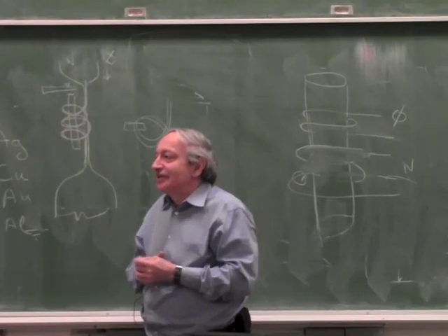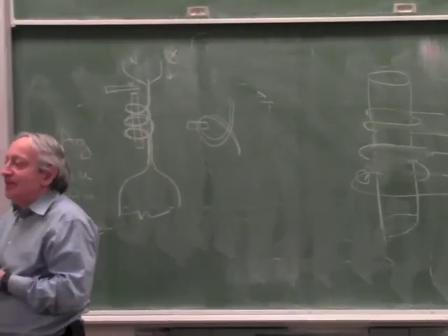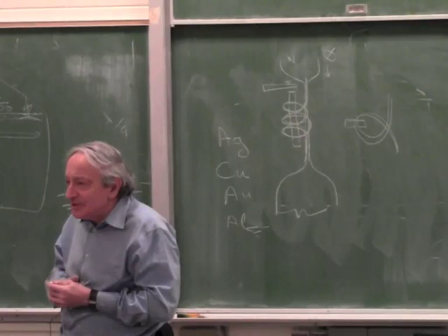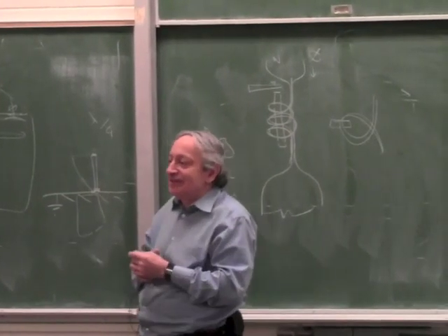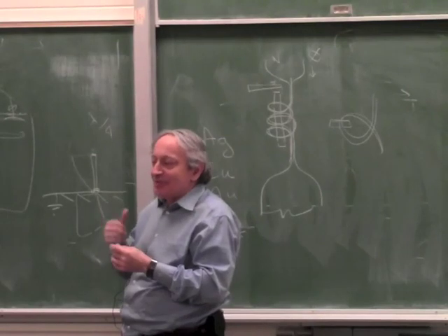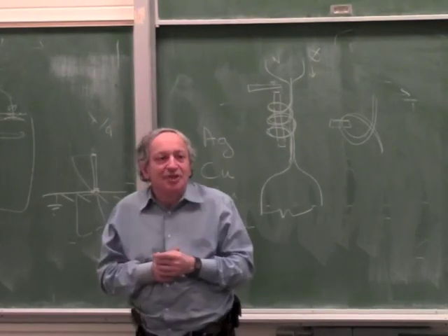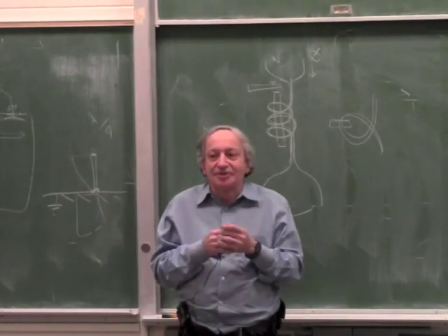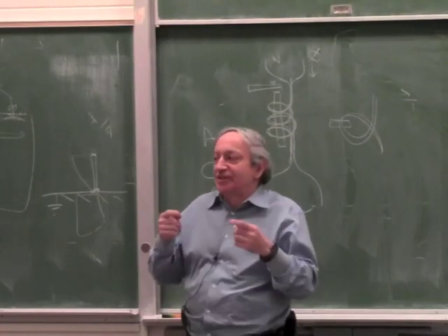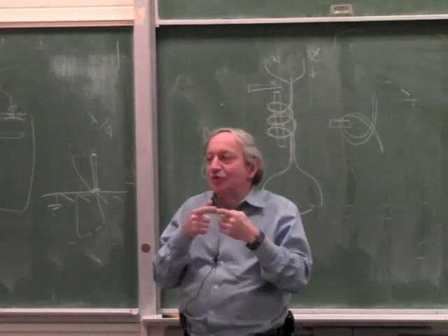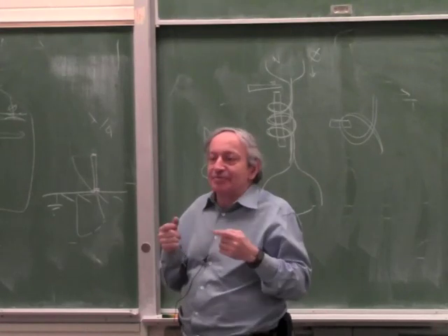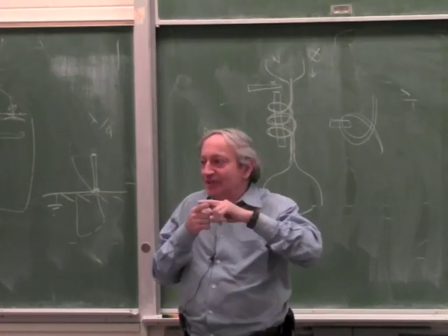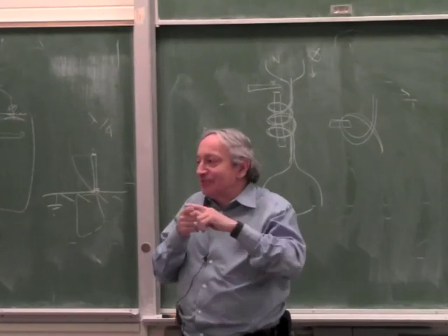Yes? I'm kind of guessing the surface roughness, like you get better connection. Not the surface roughness, but you're getting warmer. Yes? It's more malleable, so it can conform to... But copper is just as malleable. Gold has a unique property in connectors, because gold needs zero pressure to get a full contact. Every other metal needs a little bit of pressure, because every other metal has a layer of oxide on it, which could be an atom thick.